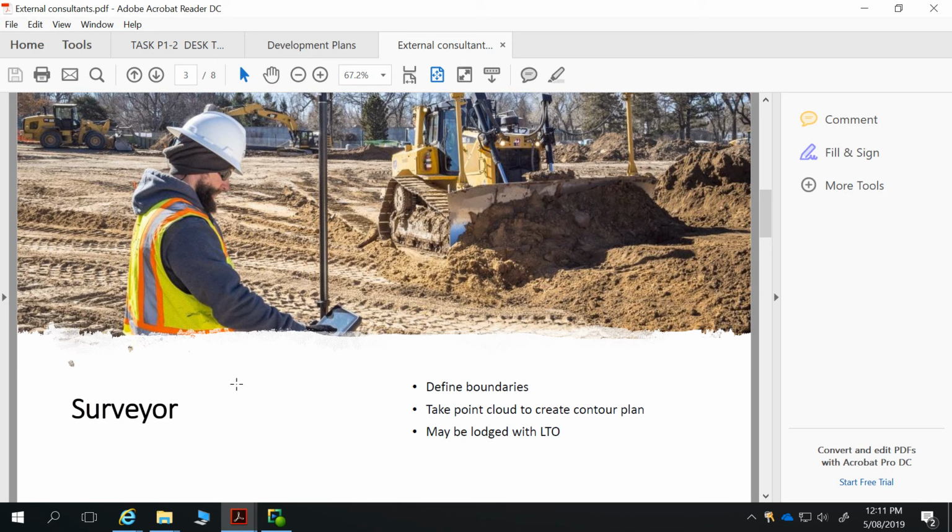We had a surveyor out going through this process just a couple of weeks ago, and what they use is a machine called a Trimble. That Trimble talks to satellites about the place until it says, yes, I can be really accurate with this point that we're at, and it can take 5 to 10 minutes to do that. So you're sitting there for a while, chatting about stuff, but the Trimble will locate this point, and it will locate that point height-wise and distance-wise in geospatial fashion. And then there's still a lot of investigation that has to happen to find old survey marks, steel pins buried almost 100 years ago, that sort of thing. But typically it's not happening in optical fashion anymore with lots of maths. All that maths, well, a lot of that maths, is done by the machine.